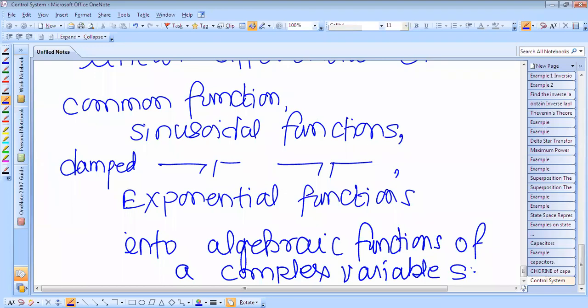Whenever the system is subjected to any input, a transient will occur in the system, and after some time the transient will disappear and your system will reach the steady state condition. Whenever a different input is applied to the system, this Laplace transform method is useful to solve the differential equation, and both the transient component and steady state component of the solution can be obtained simultaneously.